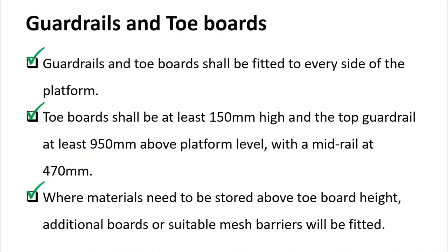Where materials need to be stored above the toe board height, additional boards or a suitable meshed barrier will be fitted. So when you want to store materials above the toe boards, then you need to make additional mesh or barriers, so that the materials will not fall down.